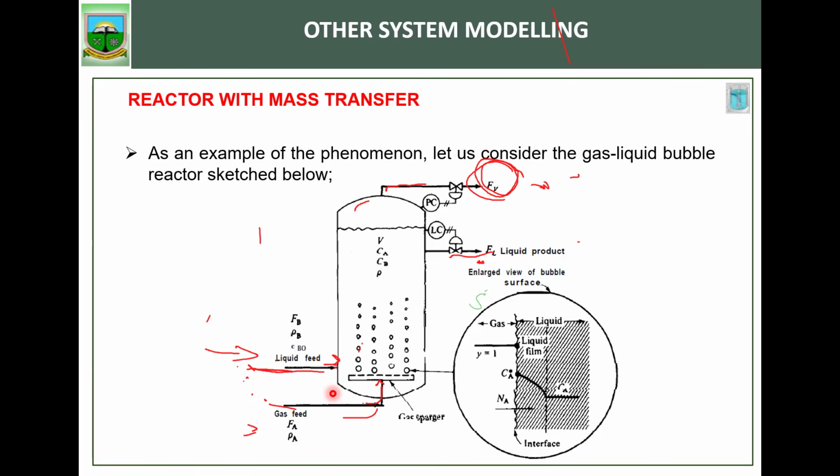The problem we have now is how this gas passes through this and ensures a good transfer. And if you remember, for the reaction to take place, the gas must first dissolve in the liquid, and that's a mass transfer behavior.